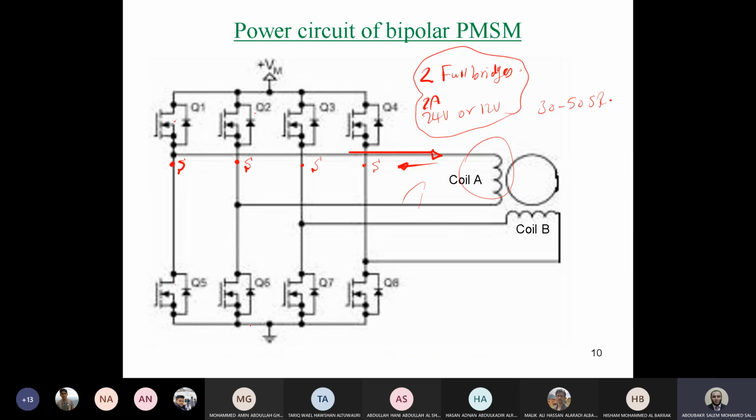However, for the lower switches, you can, because they are already common sources. But for the upper switches, the sources are different points, so you cannot connect them to ground together. Otherwise, you are going to short-circuit the whole circuit. So here you need a special circuit and drivers. You have to make isolation, and also you have to make dead band. And we will discuss, inshallah, the meaning of dead band and the isolation circuit in detail in the part on variable frequency drive.